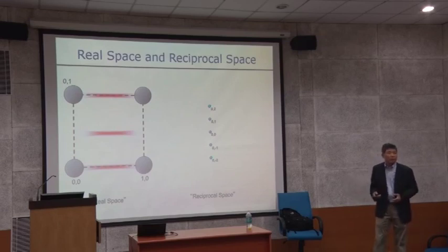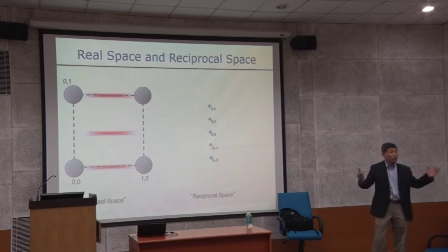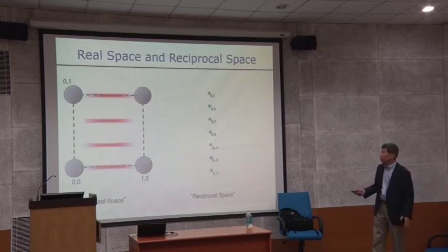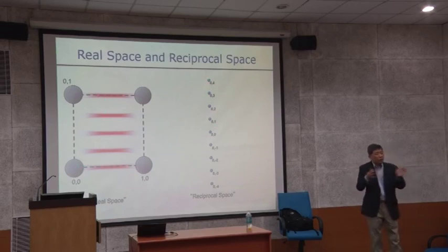What they mean is your d-spacing is longer for one here and shorter for one here, and twice longer. And then 004, 003, and here, which means 3 times longer than 001. And 004, you get here. So building the reciprocal lattice is an inverse.